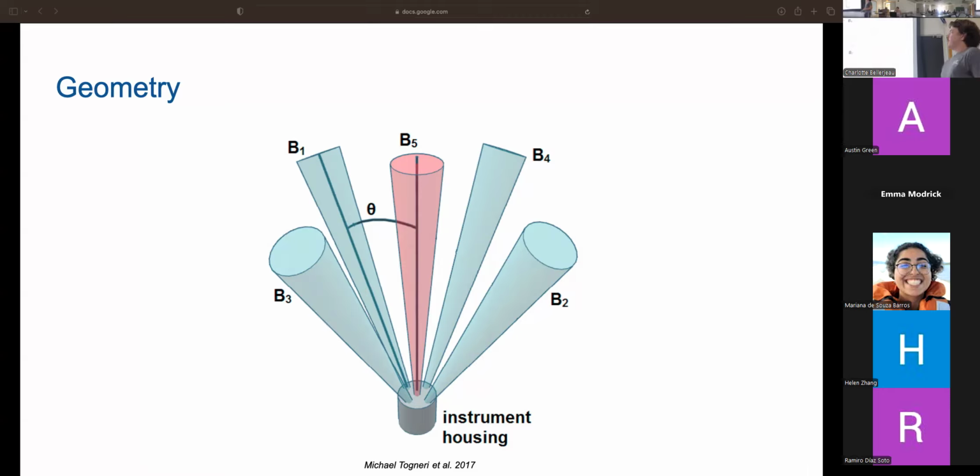But yeah, the actual angle of incidence that we care about, all of these beams are at the same angle from the center. And if you ever see these shadow diagrams, that's because when we emit a sound, it's not just a point in a direction. They actually have this kind of fun looking beam pattern, where your transducer face emits sound like that essentially.